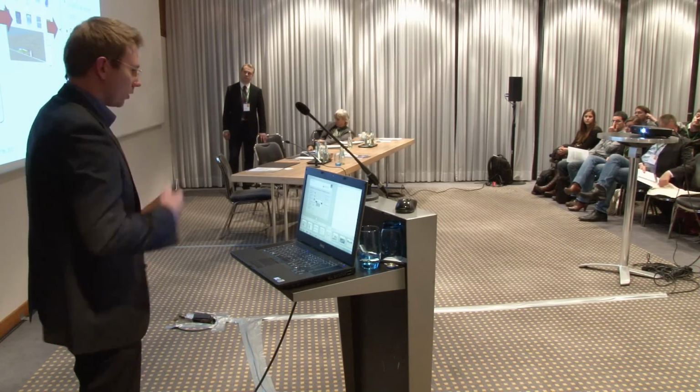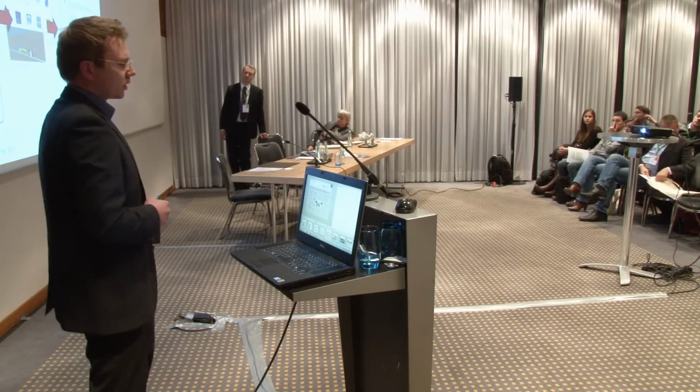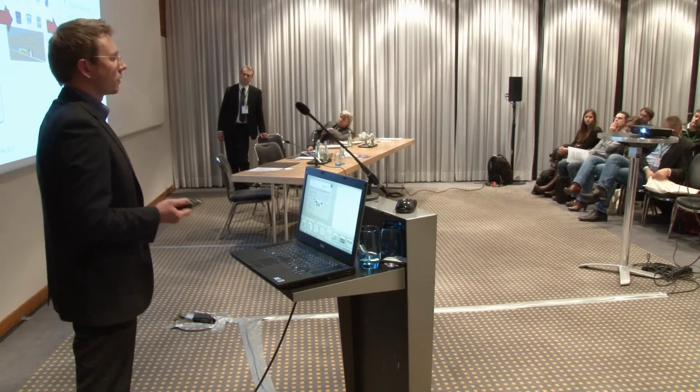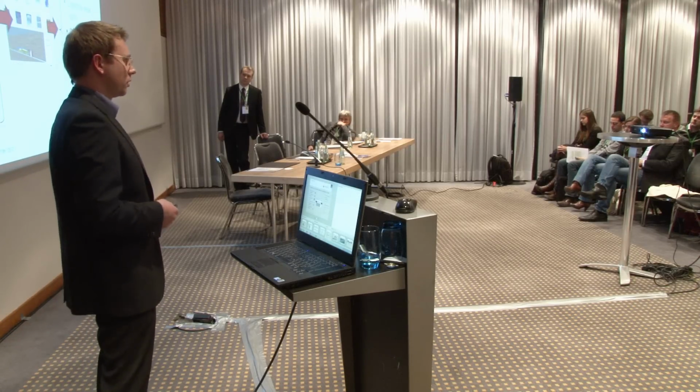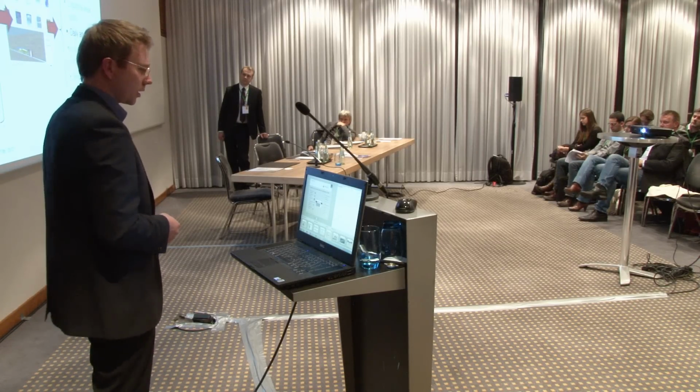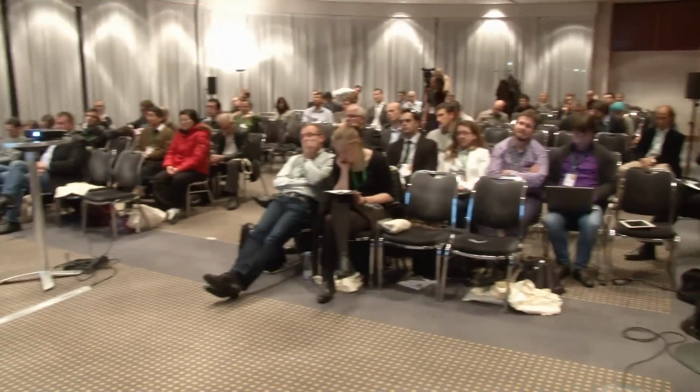Summing up the current status of the model, we are using alternating soil conditions. The dimensions of the machine and the tunnel are regarded. Process duration is put into the model, along with the probability of disturbances and the typical consumption of resources. The results we gather at the moment are, of course, the duration of the time, the impact of the disturbances, and the daily advance rate, as I showed you earlier.